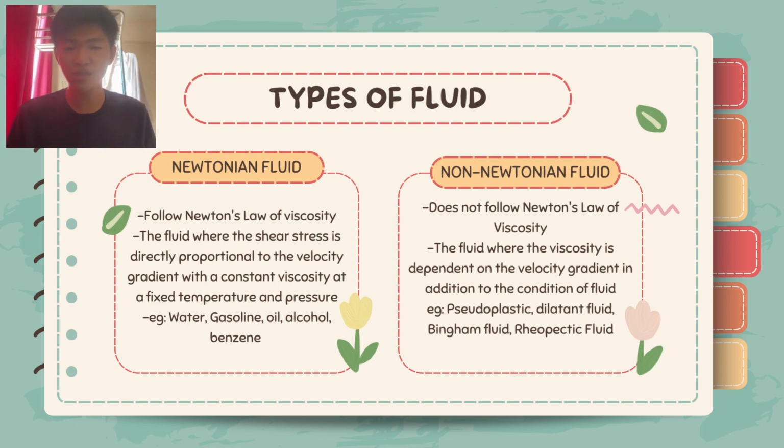For non-Newtonian fluid, it does not obey or follow the Newton's law of viscosity, and the viscosity is dependent on the velocity gradient in addition to the condition of fluid, meaning to say that the relationship between shear stress and velocity gradient is not linear.